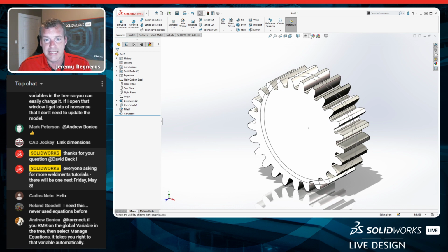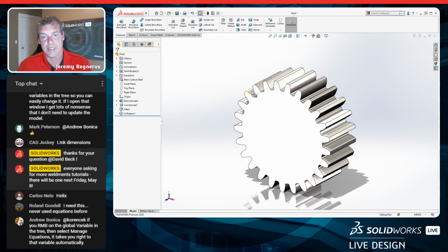I'm going to hide my sketches. So all of these view things. Here's a quick tip. I set all of these to hotkeys. Shift S is my view sketches. I turn them on and off all the time. I said Alt-A. That's my temporary axes hotkey. So look at setting your hotkeys for things that you need to do a lot.